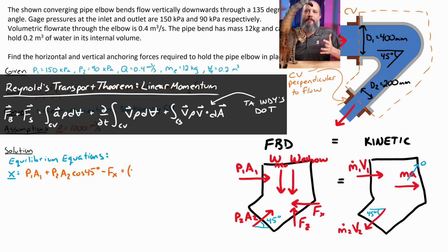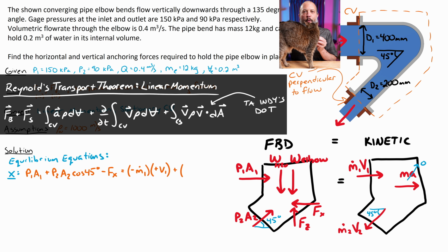All right, and now it's the moment you've been waiting for, your chance to learn from your TA Indy, what the heck is this dot? Why was that so important? The reason is to remember the sign convention. Over on your kinetic diagram, m dot 1 v looks like it's pointed to the right, so you want to call that a positive term.